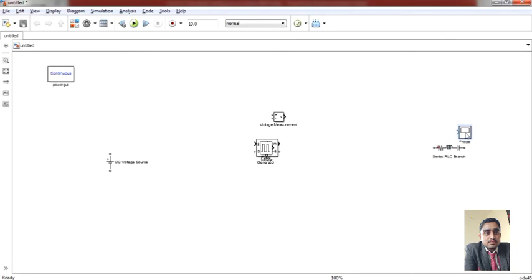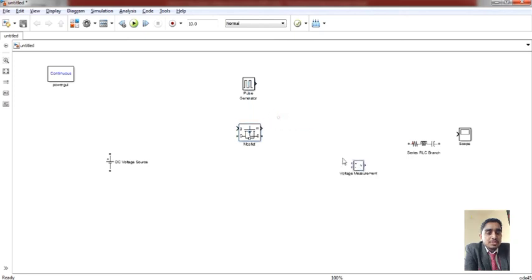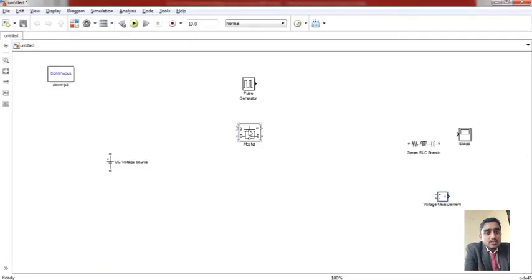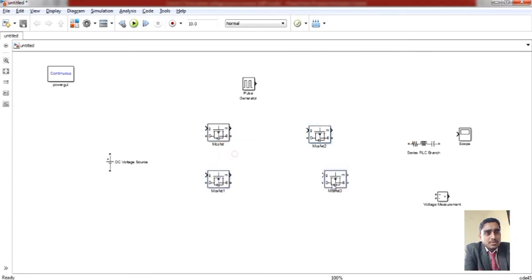This is a measurement port. It is not required, so I will remove the measurement port. You only require the last MOSFET's measurement port. So I will remove the measurement port from all 5 other MOSFETs.